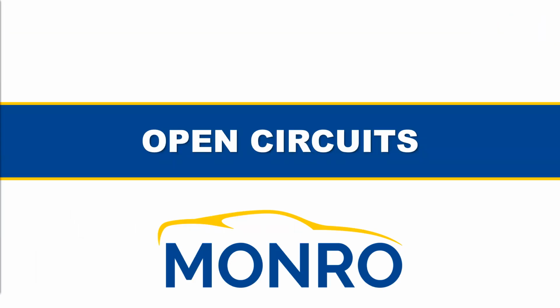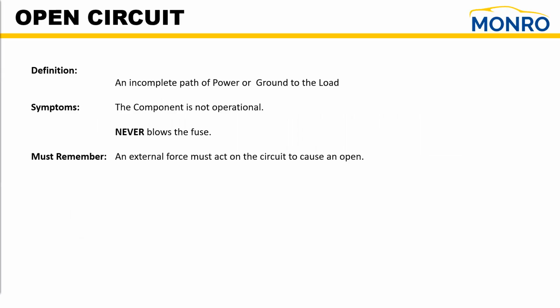So we've already reviewed the four circuit faults, but let's go a little bit deeper today into an open circuit. And you'll remember we defined an open circuit as an incomplete path of power or ground to the load. Then the symptom was the component's not operational. And what we know is in an open circuit, the fuse never blows. Remember, what causes a fuse to blow? Excessive amperage. And if there's no current flowing, the fuse will never blow.